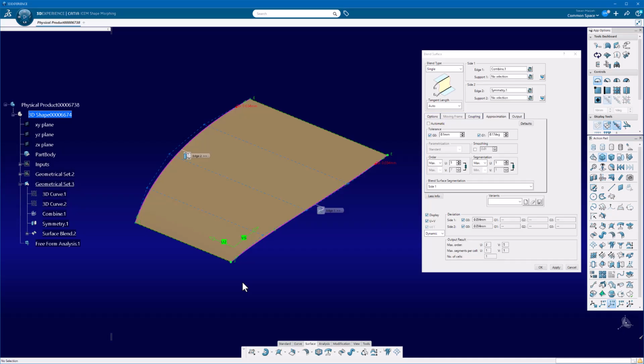Now, other places that I do use this is when I'm going to make another surface come down from that corner down. And I don't want that surface to have all of that complexity, and I want to approximate it, smooth it out a little bit. And to be quite fair, chances are this little amount of deviation in the long run really means nothing. And the reason why it really means nothing is because when I go in and create the blend between these two, whatever slight little deviations along that edge that may exist aren't going to matter at all. Okay?